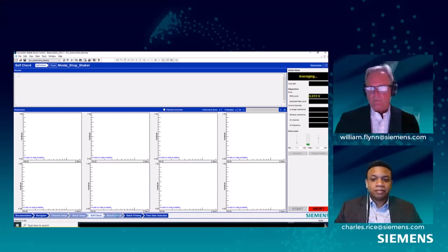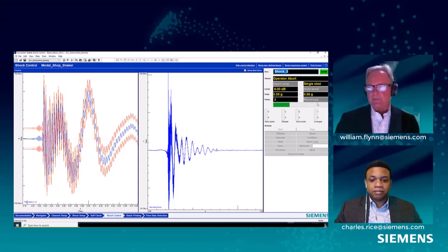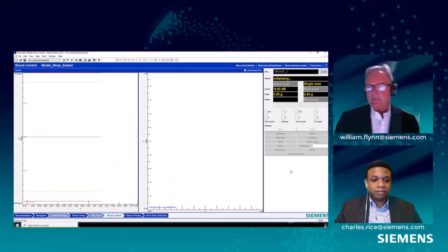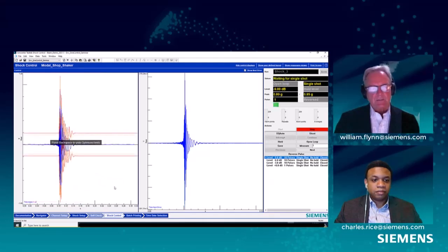And then we'll go right over to shock control. So our coherence looks good, pretty confident in this setup already. Start the test, arm it first, and then initialize the settings, start, shoot, and when I optimize limits, it looks a lot like the measured pulse, but this is all based on an SRS. So maybe that measured pulse was from the SRS response. Can't remember for sure.